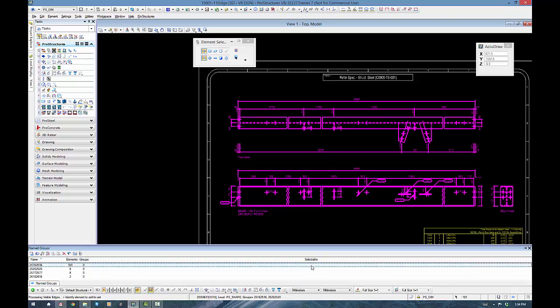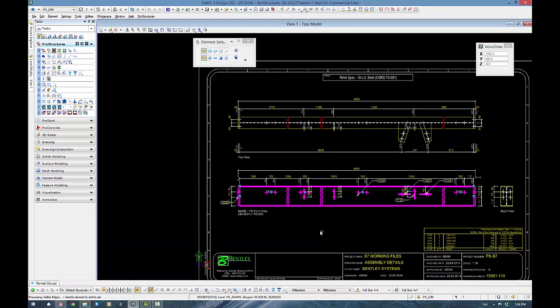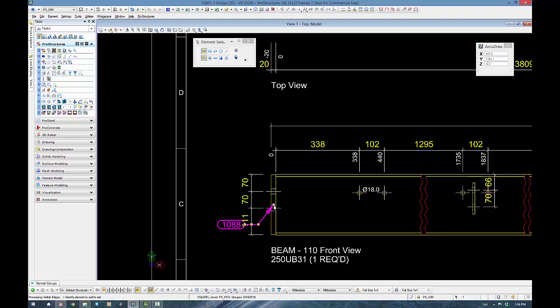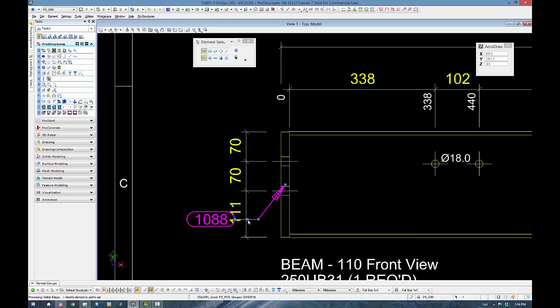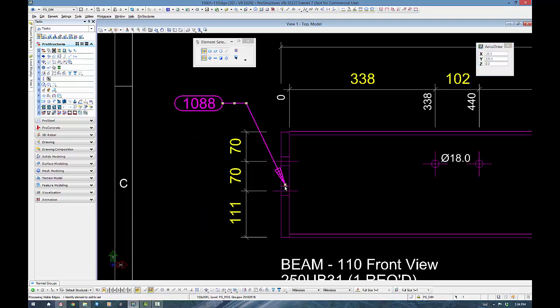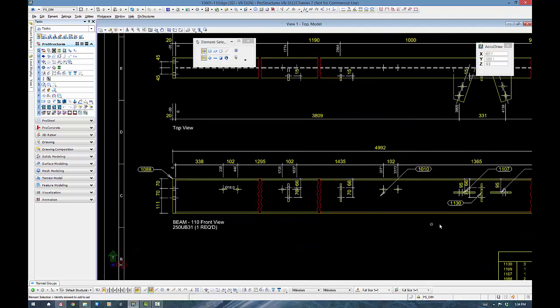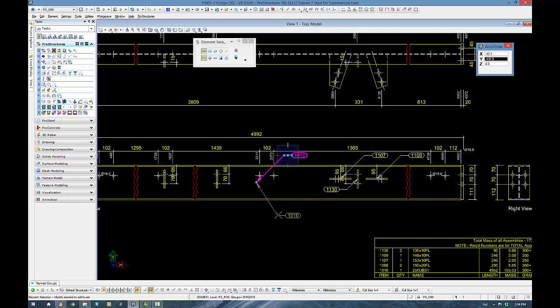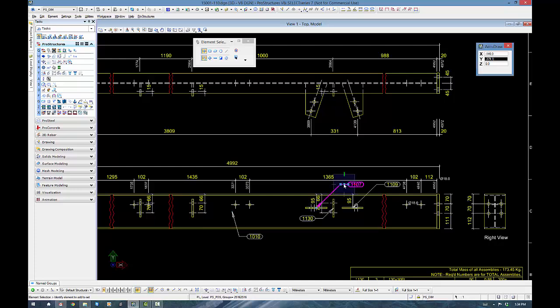That is put in through the group data, okay, in my system. Now don't forget, same story with the selectable detail block. Things like pos flags, if you want to move the pos flags around, you can see you've got 3 little grips here on the horizontal and one on the arrowhead. If you grab that middle one, you can just move these around and grab one for the arrowhead, drag it to where you want. Beautiful editing. Okay, very, very user-friendly with all of this sort of work if you need to do it. Personally, I like the bracing cleats up in the view so that people can associate what the actual arrow is pointing at. So I would kind of present it like this.